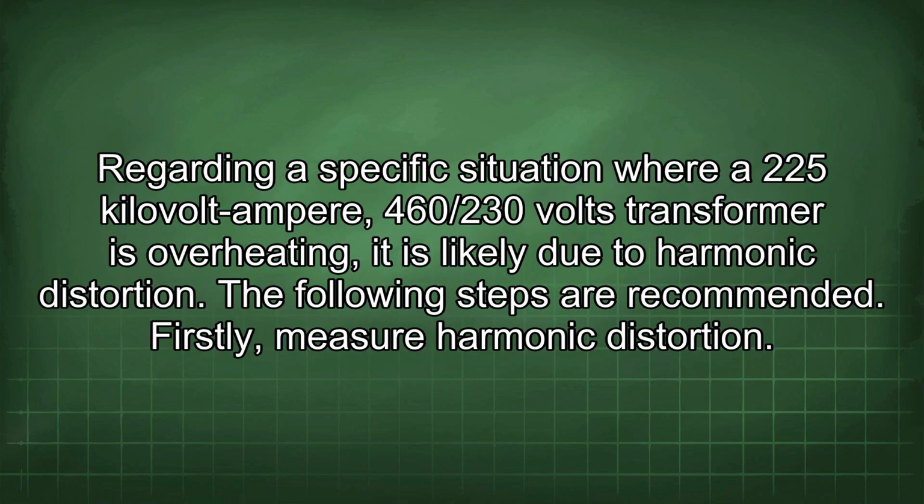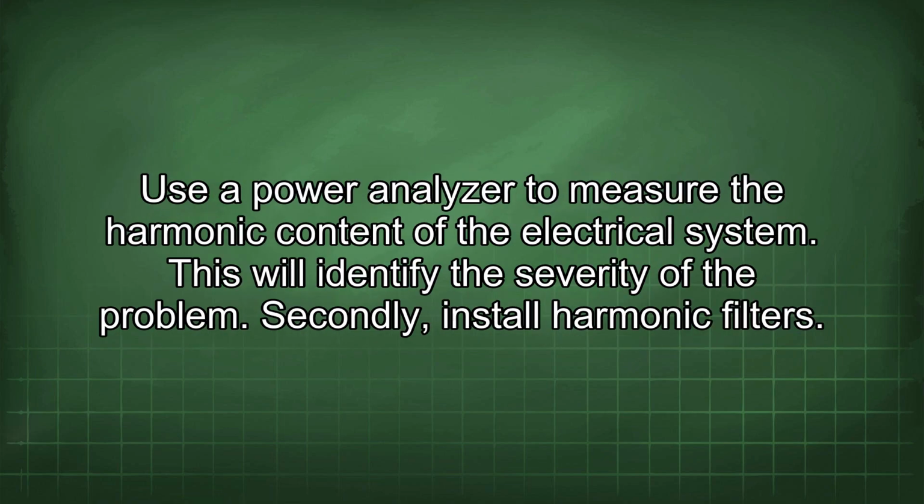Regarding a specific situation where a 225 kVA, 460/230 volts transformer is overheating, it is likely due to harmonic distortion. The following steps are recommended. Firstly, measure harmonic distortion. Use a power analyzer to measure the harmonic content of the electrical system. This will identify the severity of the problem.